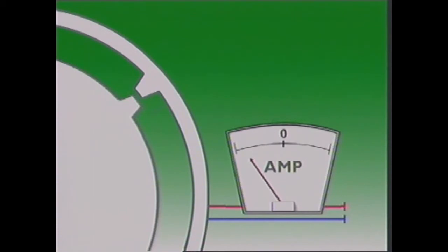This time, current flow is in the opposite direction, and the polarity is now said to be negative. Since polarity changes every time the teeth approach and leave the stator teeth, the voltage produced is an AC voltage, and current flow is an alternating current.